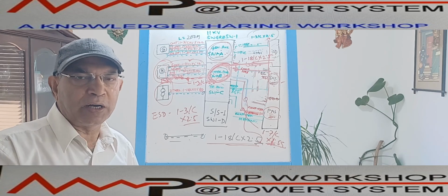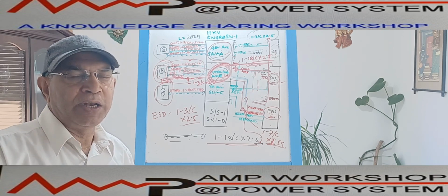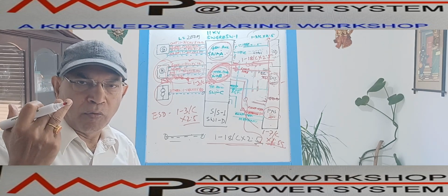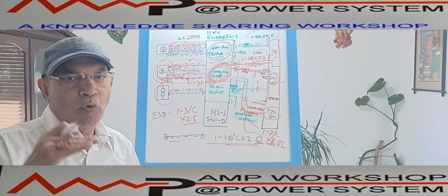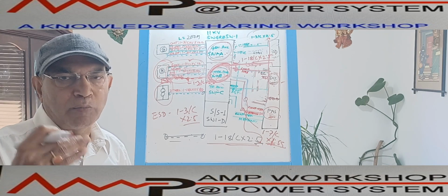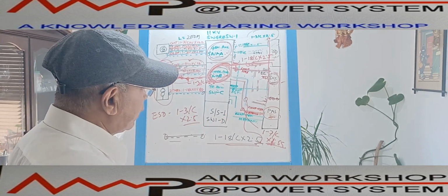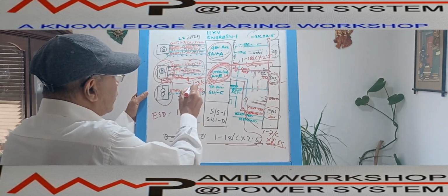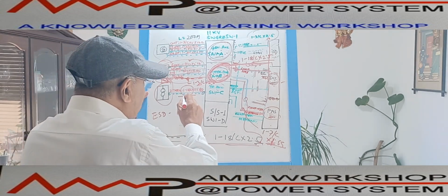Each device has 2 contacts. Like winding temperature has 2 levels, winding temperature alarm and winding temperature trip, so there are 2 contacts coming from the indicator. Similarly, the oil temperature indicator has an alarm contact and a trip contact. The oil level indicator has oil level low, so there are 2 contacts. The pressure release device or Buchholz has operated, that is also a contact. All these statuses we bring to the switchgear, either for tripping purposes or for monitoring purposes. For that reason we considered one 12-core cable. There are 4 devices, 8 contacts, so a 16-core cable.